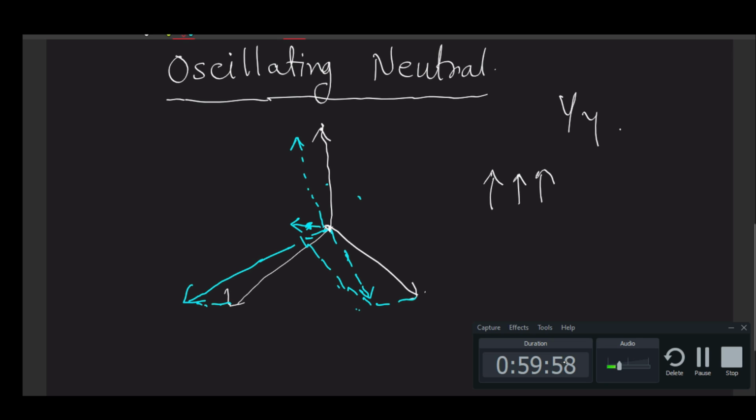Now if you consider some other instance, when they are in this direction, your neutral, instead of being fixed at a particular point, will make a complete rotation around your actual neutral point with a certain voltage, and that will cause the appearance of a huge unbalanced voltage across different phases at different times.